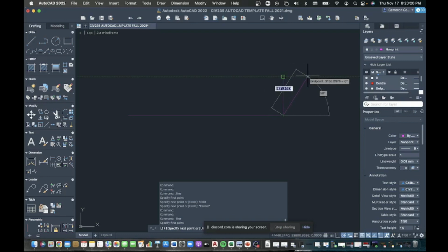I'm going to go across, make this 45 degrees, and then I'm going to tab back until I reach there. You'll see your cursor snap to that line if you've hovered over that point before. There's going to be a little X there, and that's going to be our first line.